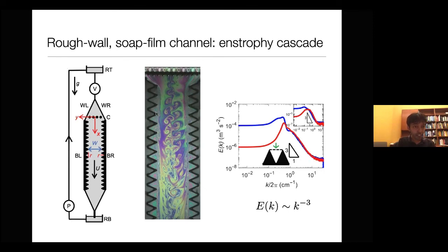And then we measure the friction on the rough wall. To measure the friction on the rough wall, you need to measure not only the viscous stress but also the Reynolds stress. Earlier, you could get away with the viscous stress because at the smooth wall, the Reynolds stress goes to 0. But at the interface of the rough wall, there's a substantial, in fact dominant, contribution from the Reynolds stress. So you have to use the technique of particle image velocimetry, which is what we used here. And we measured many, many different roughnesses. For the smooth wall there's just one kind of wall, but for rough walls you have to change the roughness, so it involves a lot more work.